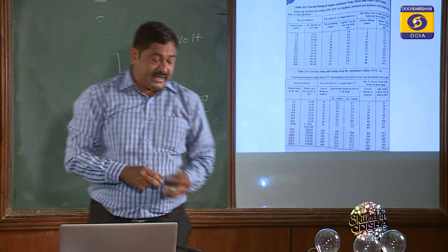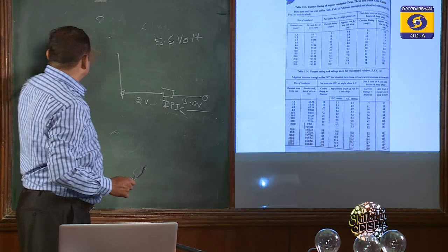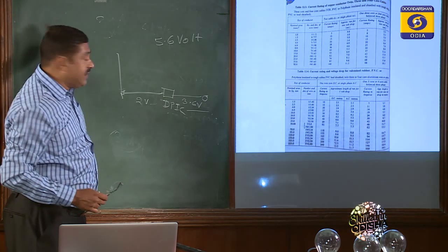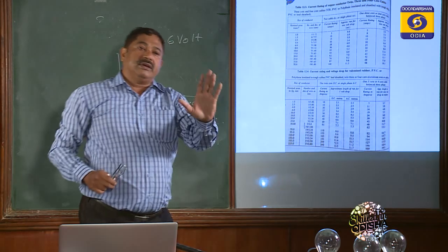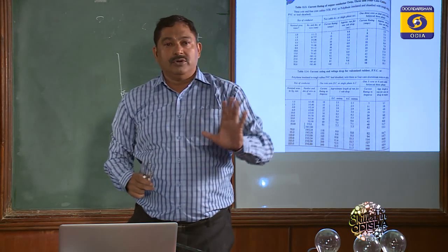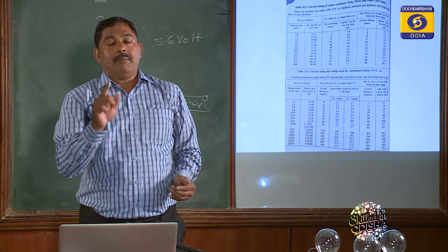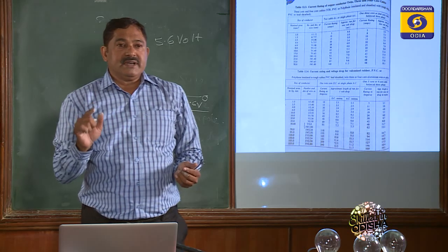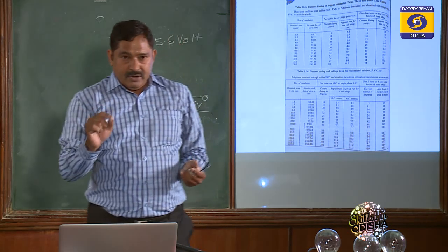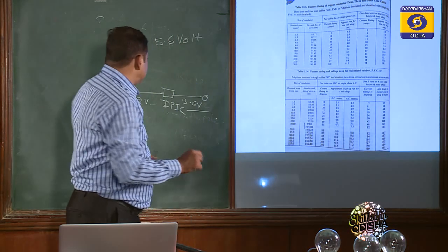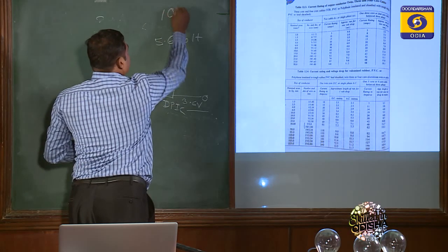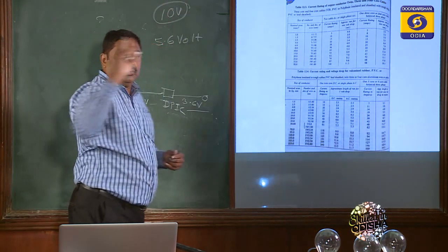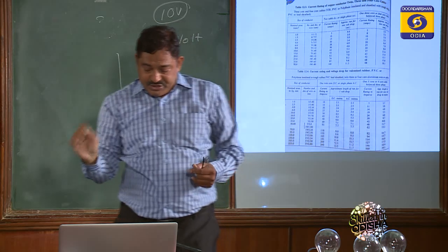Often we find this thing. And another, from the transformer secondary to the pole, we keep another 5 volt margin. So total 5% LT voltage drop, around 10 volts, we allow from the transformer to the switching points.